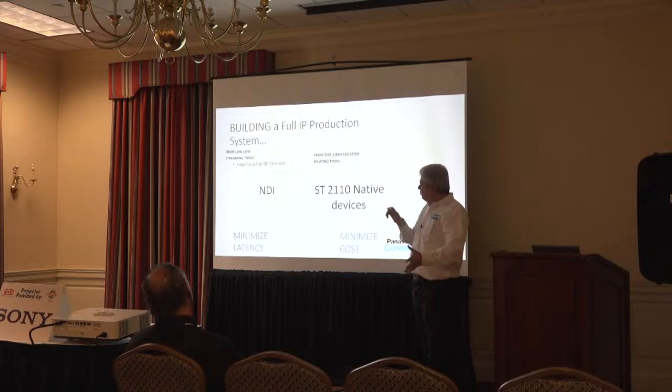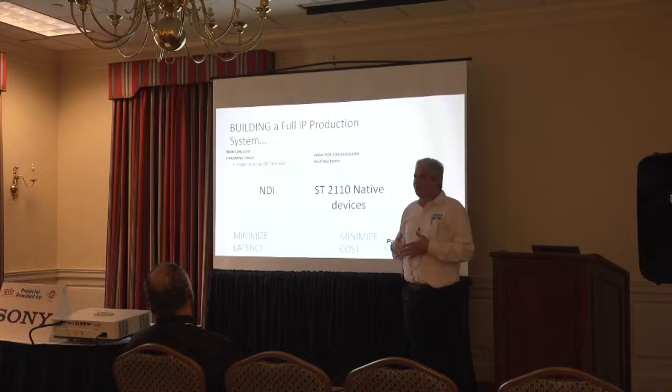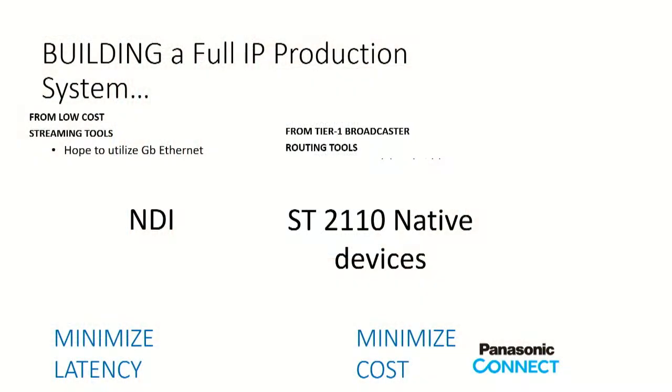So before ST2110, NDI became very powerful because it had auto discovery, and that made life easier. You connect to the network, and it automatically tells you which camera it is, which company it is, and what model number it is. So it has auto discovery tools built into it. And that was the advantage. The disadvantage was it's compressed and you have to uncompress.